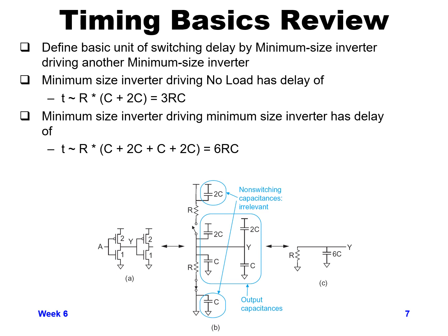So our unit inverter is a size 2 over size 1 PMOS to NMOS ratio, and it's driving another unit size inverter of PMOS size 2, NMOS size 1.